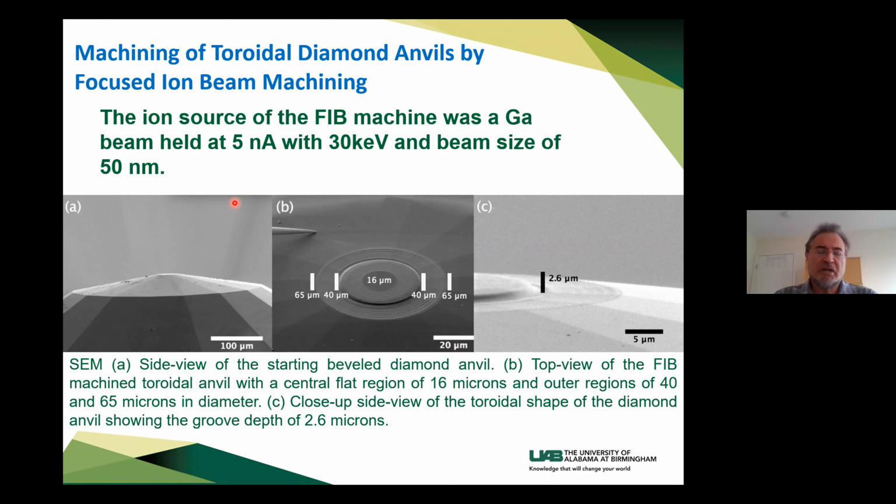Okay. Well, I thought that one point of this groove is that it allows an increase in contact friction. Because without the groove, you have sliding between the sample or gasket and the diamond, and the friction stress is lower than the yield strength in shear. The same was true for cemented carbide anvils for diamond synthesis. So the groove significantly increases friction, because then sliding occurs within the material.